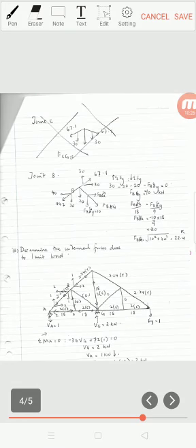This is the dummy structure. When we put 1 unit load at E and we throw away all the applied loads, it becomes the dummy structure. Again, I first find all the reactions by taking moment at A equal to 0. So these are the reactions that I got. Vg is 2 kilonewton acting upward, and Va is 1 kilonewton acting downward.